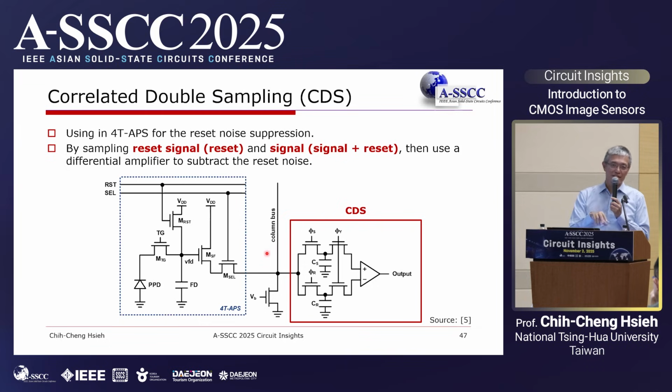And the other thing is there's no accumulation. That means there's no in-pixel gain. So the sensitivity is quite poor in DVS. That causes a lot of false alarms. Because it uses events to do the motion detection, but because of the noise and the poor signal-to-noise ratio, it will cause a lot of false alarm issues in this field.